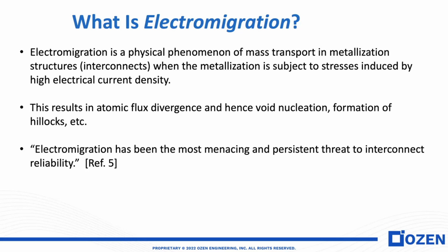What this results in is atomic flux divergence. And this atomic flux divergence, either positive or negative, is either going to create void nucleation or the formation of hillocks.